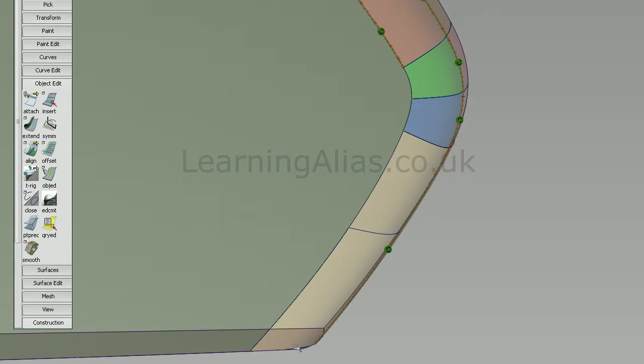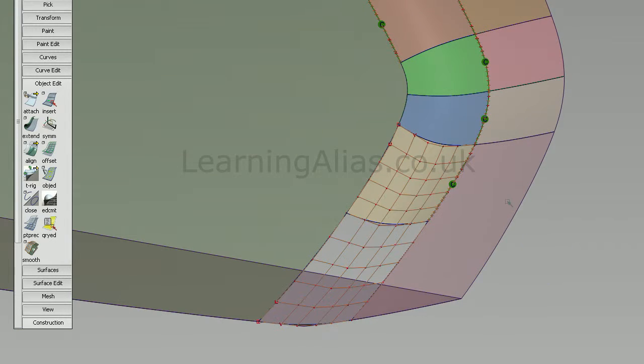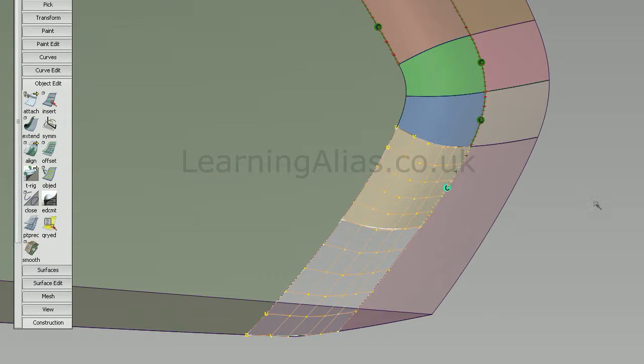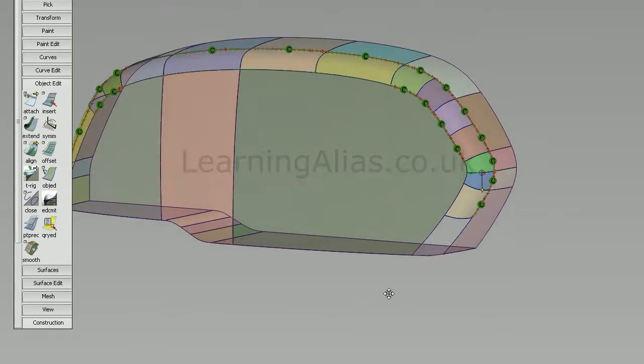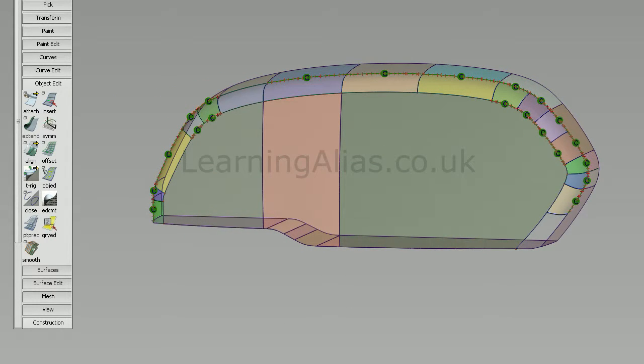Usually before splitting surfaces up using this technique, when we're trying to solve continuity issues, I would usually try direct modelling individual CVs or holes to try and gain the continuity that I was after. However, having done this model a few times, it turned out the surface was just doing too much work and needed to be split into 2 or more separate surfaces. So it was kind of a last resort. Always go for direct modelling first.